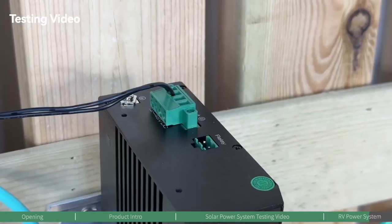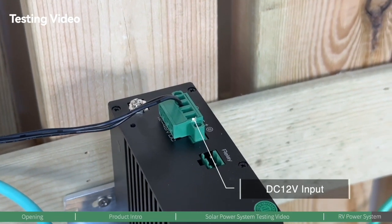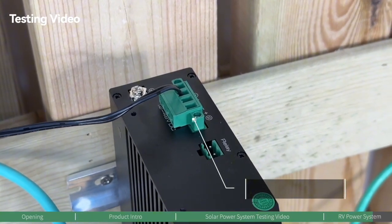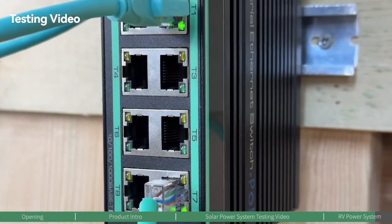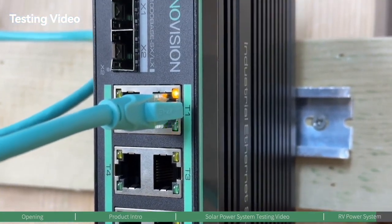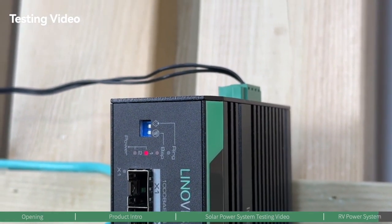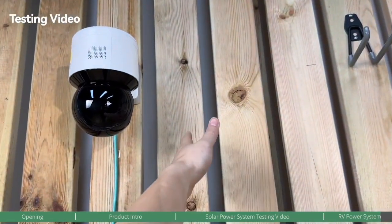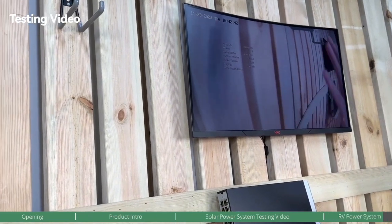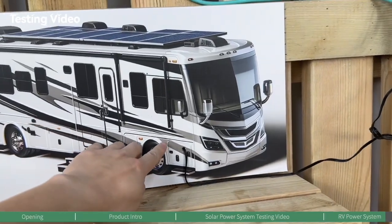At the center of this setup, we have the voltage boosting PoE switch from LINOVISION. This PoE switch can convert and boost the DC 12 volts power from the electrical system of the RV into PoE compatible power, adhering to IEEE 802.3 af/at standards. These standards ensure that devices receive the precise voltage and power level suitable for safe and efficient operation.